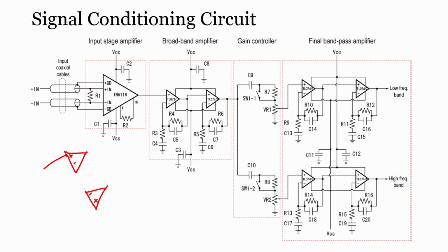So, this is one input, I can call it IN plus, and this is another input, IN minus. As most people know the configuration of the instrumentation amplifier, I am not discussing much about it, but I will draw the circuit and construct the same in order to visualize the functionality. The negative terminals will be connected at this point, and this constitutes the gain, whereas a third operational amplifier is used as a differential amplifier. Okay, I will draw it properly.